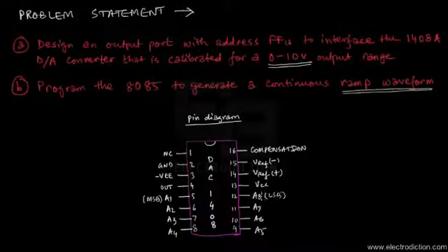the chip. While working with the 8085, in order to make provision for accessing this particular chip only when the address FFH is given out by the 8085, we would need to connect some other device along with the DAC, maybe a latch chip. Yes, you can say that. A latch is quite a good gateway under this sort of situation.